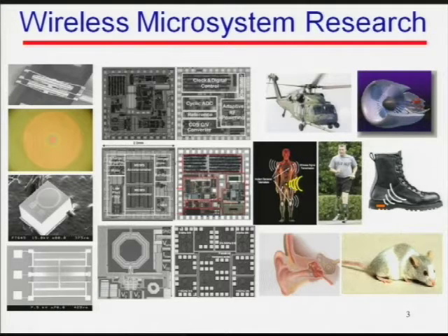And this is a top view of a silicon carbide capacitive pressure sensor that was fabricated in collaboration with Professor Chris Zorman. To achieve high temperature capacitive sensing capability, we demonstrated sensing up to about 400 degrees C, which can be used for various high temperature engine pressure sensing.